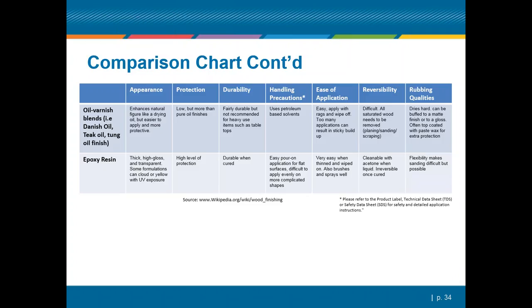If I had to pick one product line that's a one-size-fits-all, I'm very prone to move to polyurethanes as that system. It's an easy field-applied system, relatively easy to prep for, and they dry fast enough that you should be able to get a coat per day, minimizing the time it takes to finish a project. So if you wanted one size fits all, I would look at polyurethanes.